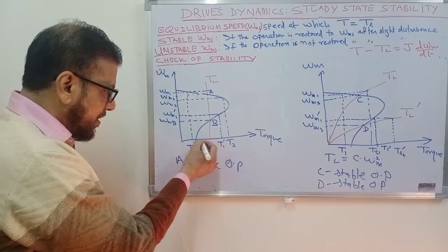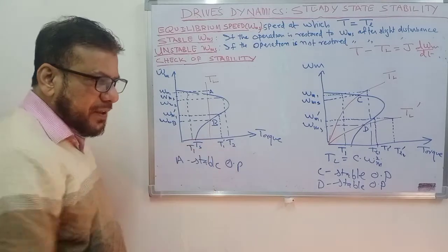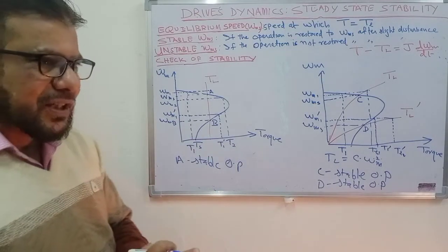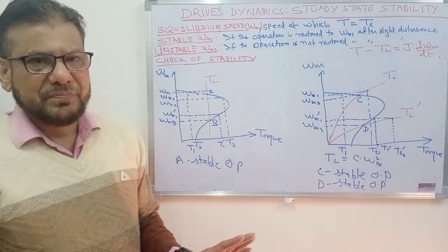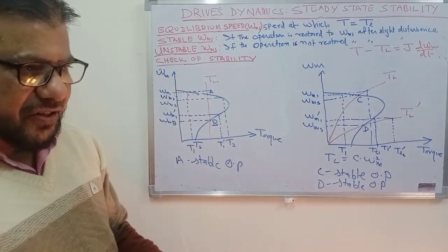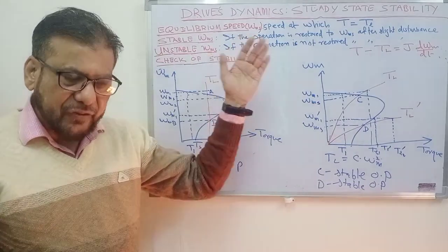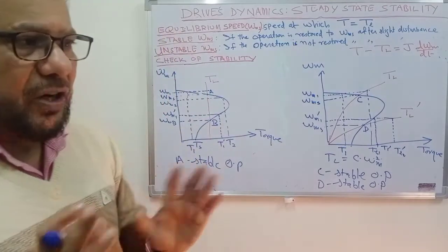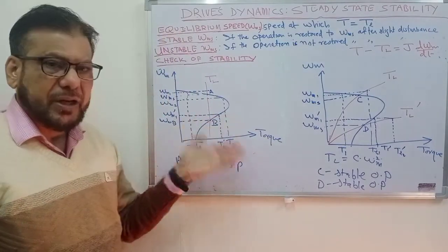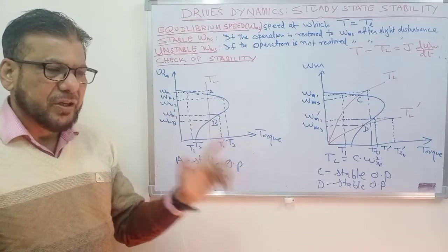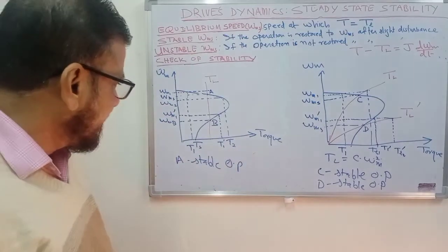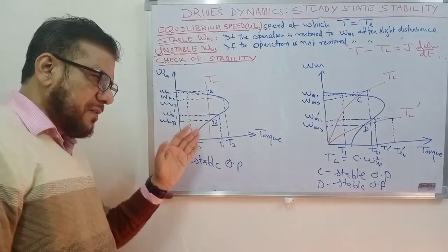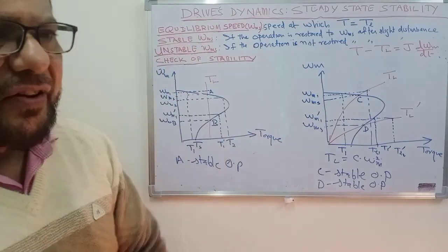You start the motor. This is the load torque. This is the starting torque. Starting torque is less than the load torque. So this means that the motor will not start at all. Motor will remain stationary. It will start drawing heavy current from the source, and if you leave it connected, the motor windings will be overheated and will burn out. So you have to stop the motor immediately if this happens. And you can connect such a load when the motor has started and started running.